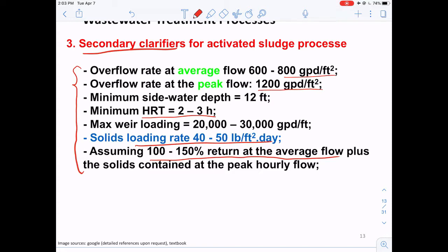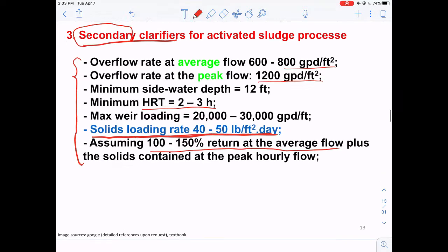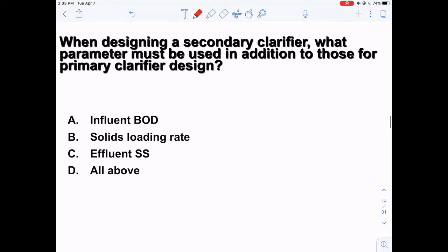But here we're just going to use the concepts of the primary clarifiers. For the primary clarifiers of the wastewater treatment, the surface overflow rate is going to be very important. But for these secondary clarifiers, we also need to consider the suspended solids amount, because the mass of these grown microorganisms is also going to affect the performance of the secondary clarifiers. That's why we want to operate them under a range of suspended solids.